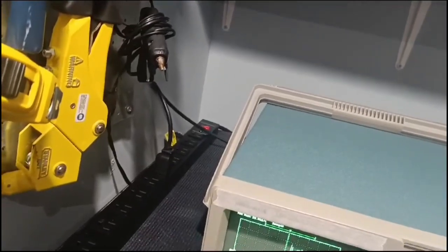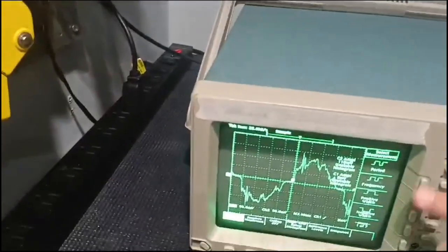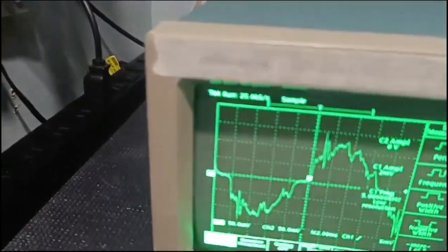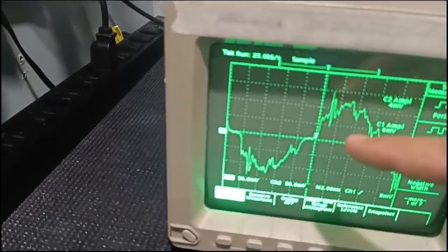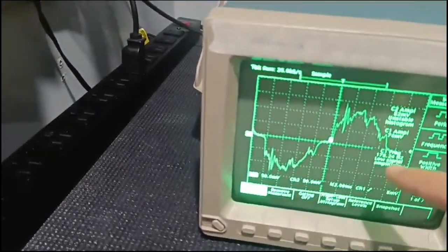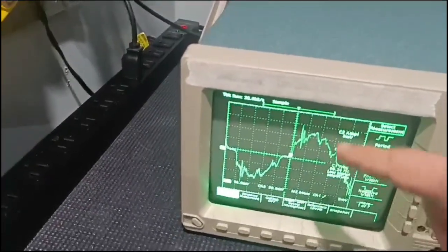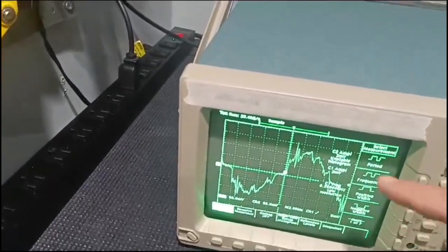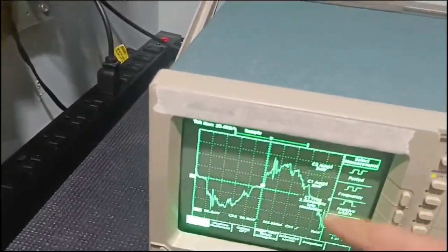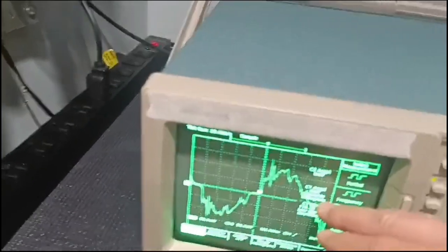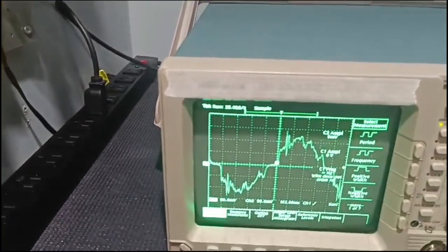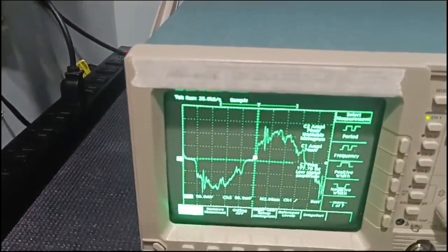So the frequency, let's see if we can measure the frequency. We can do frequency right here. We have roughly 60 Hz, but let me tell you something, it's very difficult to capture the frequency with this kind of pattern, because we need to export this data into numerical software and perform a polyfit that allows you to obtain a smoother sinusoid. As a matter of fact, the pattern is so rough that even the amplitude has a certain difficulty to be calculated in these configurations. Alright? Now, the next video will be made with the parallel configuration.